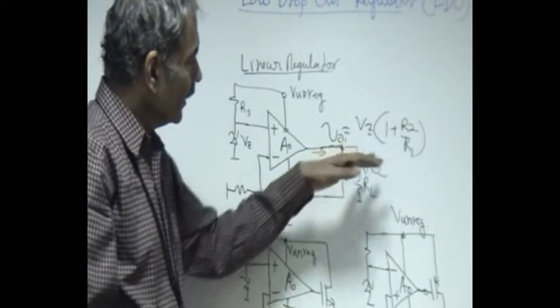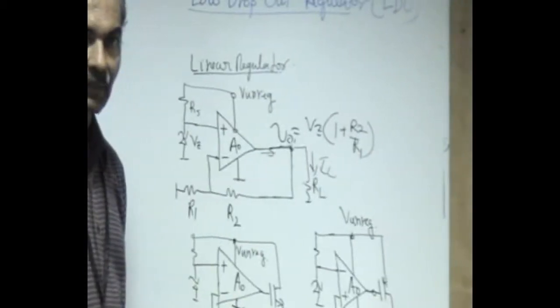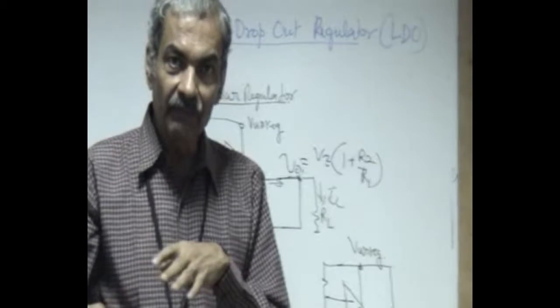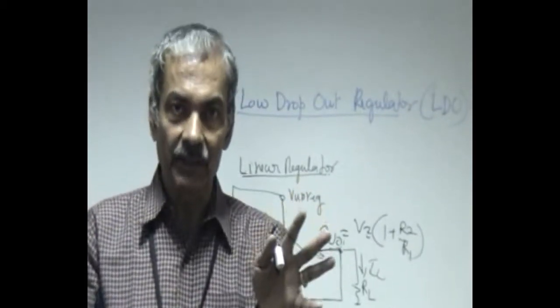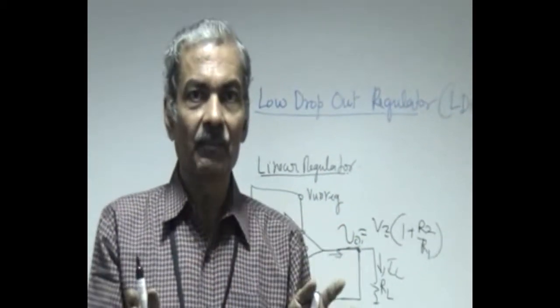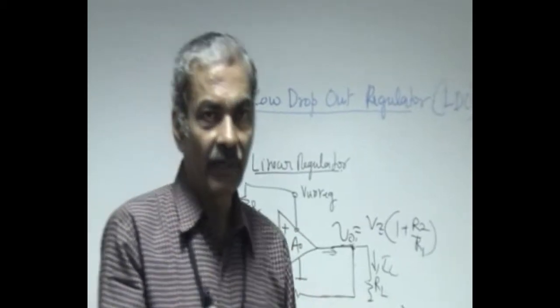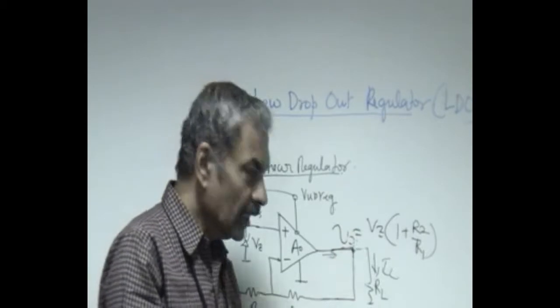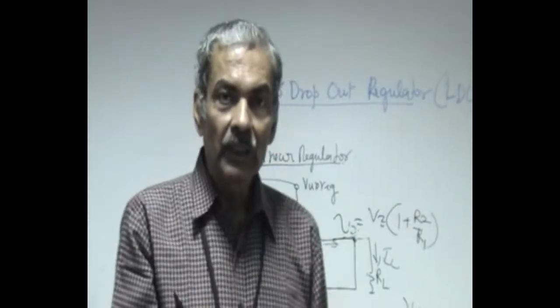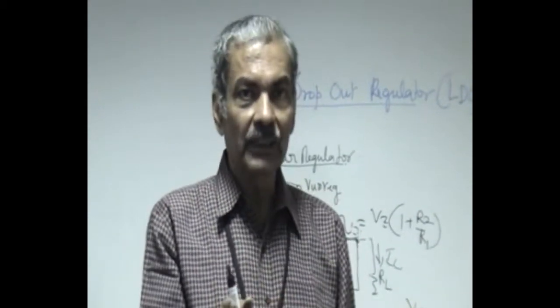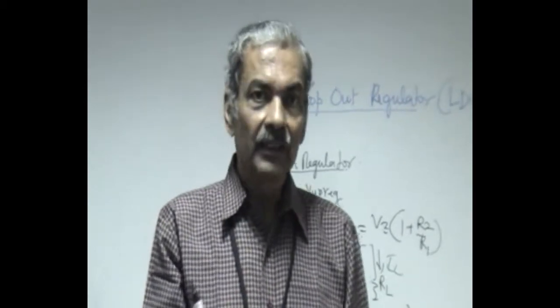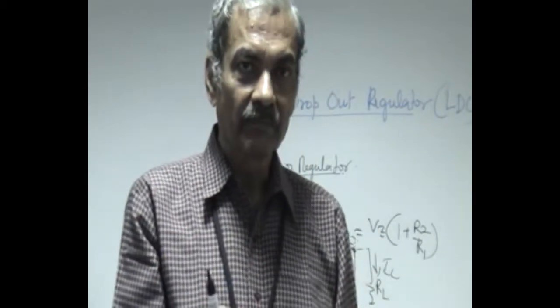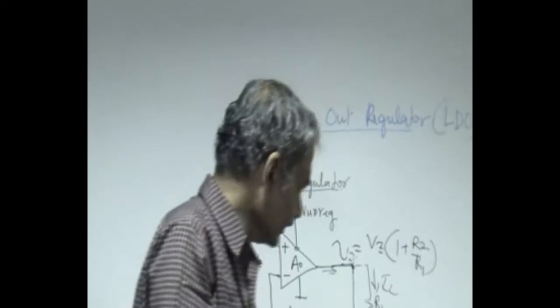And then the output impedance, which is a small signal parameter, has to be measured at the frequency at which this is supplying power, right? So if it is supplying power to, let us say, a high frequency stage, it is at that frequency that you have to measure the output impedance. That output impedance should be low so that other circuits which are deriving power from the same supply do not get the feedback from this particular high frequency circuit that you are using.